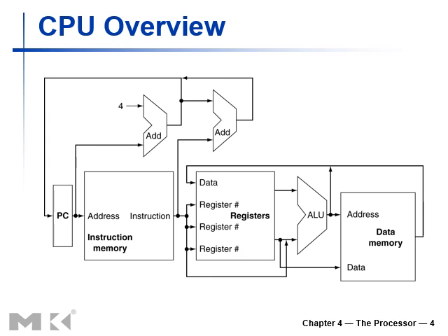Well, coming to the next slide, this is the basic structure, or the basic components, that are being used in a single cycle processor. Why do we call it a single cycle? We've discussed earlier that all the instructions are processed in one clock cycle. That's why we call it a single cycle. And that sort of processor has a CPI, cycles per instruction, equal to 1. So if you see the basic structure here, these are the basic modules, and definitely with the passage of time, some new modular components are going to be added in this processor.